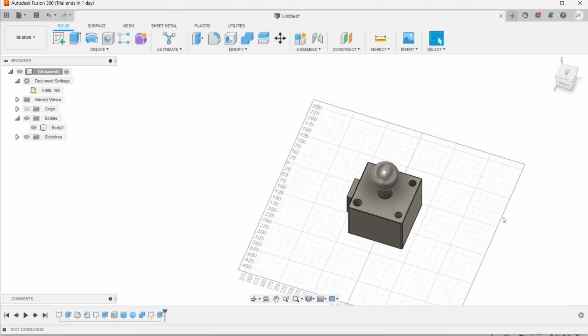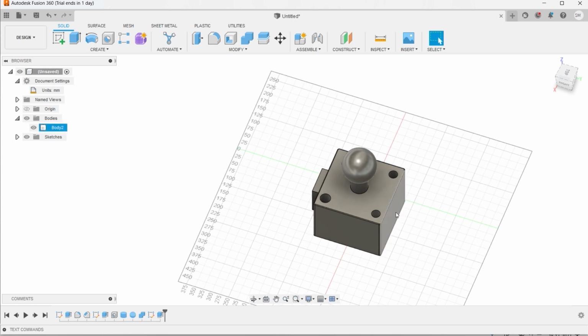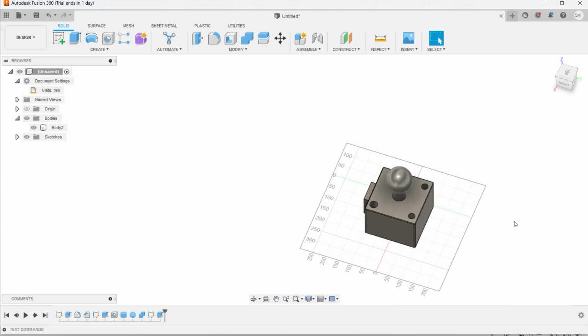So the option is we need to create the same thing again, and we need to extrude this one on the other side. If we make a mirror of this one with respect to a specific plane, then the similar object will be produced. But we want to produce this object with different depth of extrusion. In that case, what we have to do? With the help of projection, we need not draw this one again. We can bring the previous drawing on this surface, right?